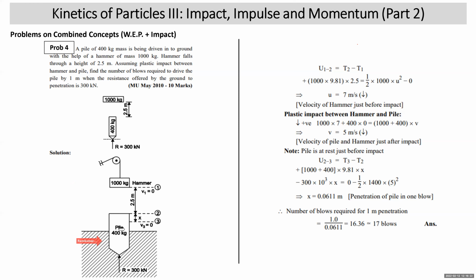So what happens when this pile reaches sufficient depth? There will be some ground resistance offered by the soil to the pile, so that this pile is in a position to take care of the load. Sometimes this pile will touch some hard surface, then also it can take the load. This way number of piles are erected at very close interval. And then a pile cap is constructed like a slab. Then the foundation base is ready. So this is the pile foundation where pile is being driven into the ground.